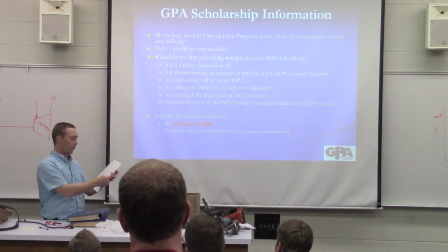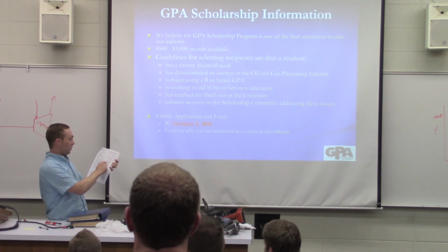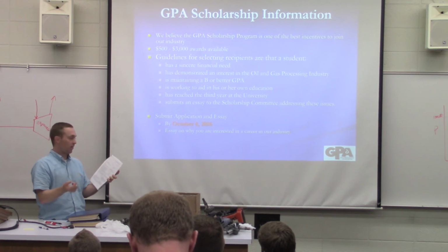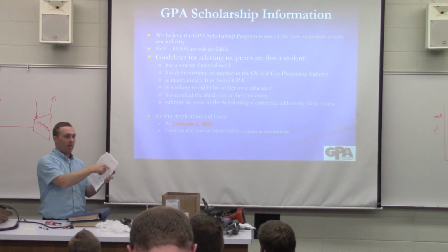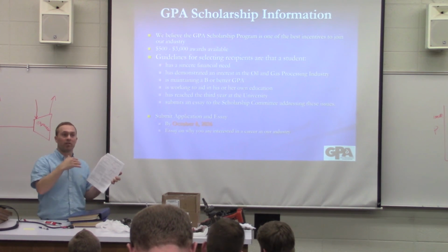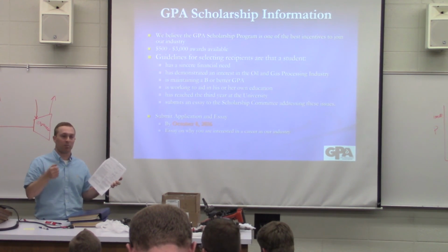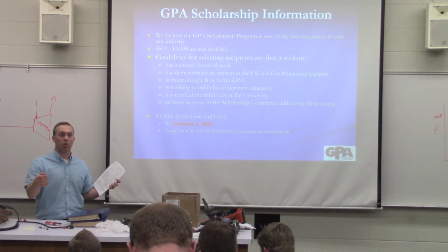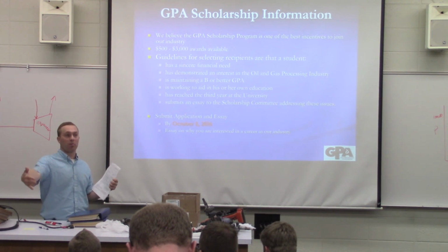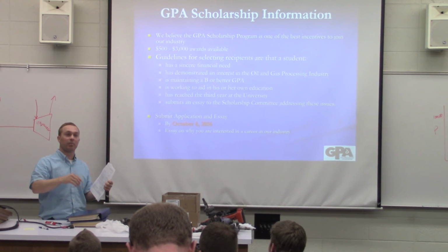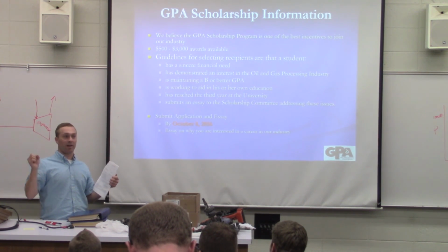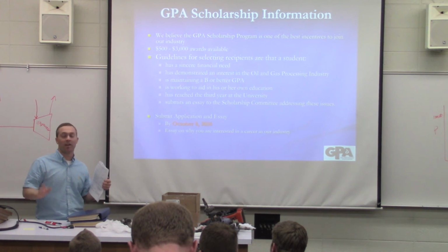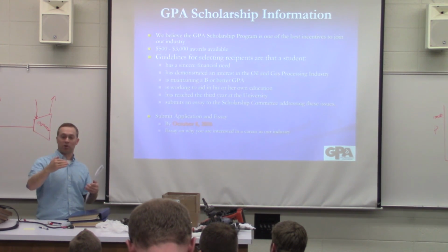But it just becomes so much more real life when you say, well, what determines this pressure PA? That depends completely on your temperature for condensing the gas when it comes out of the compressor. And you realize, well, okay, there's a big difference summer to winter. So you have more than enough compression in the winter time, but in the summertime, you're condensing it by blowing air on it, it's just going through some fans. And so that determines what that discharge pressure is.